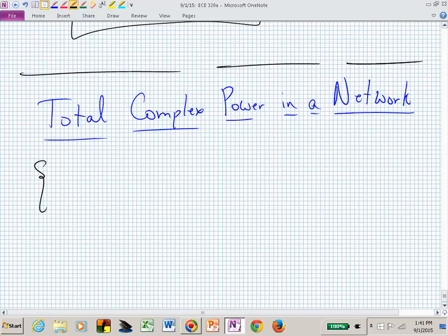Well, you need to be careful if you're playing with power, but you already know that since you're taking this class. You're trying to learn the right way to do it. But how these loads are interconnected is irrelevant. You can now take all of these different loads, no matter how they're interconnected, and add up their real parts and their reactive parts, and the sum of those two give you the total complex power, irrespective of how they're connected in series or parallel. That's what I'm trying to say in brackets.